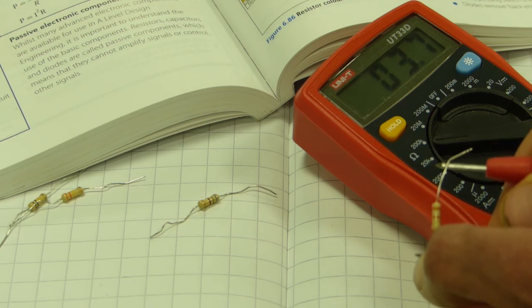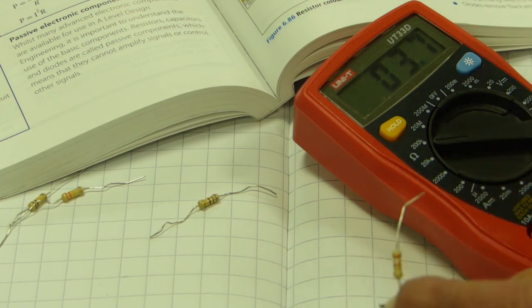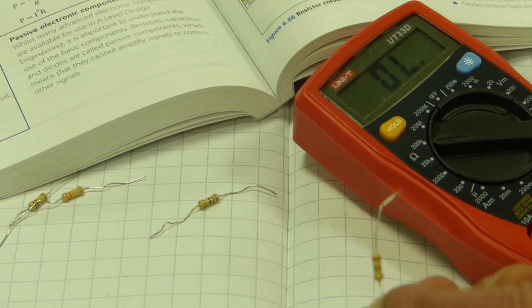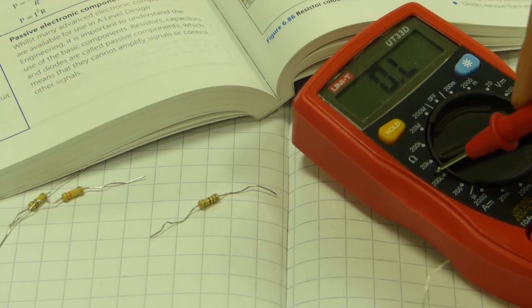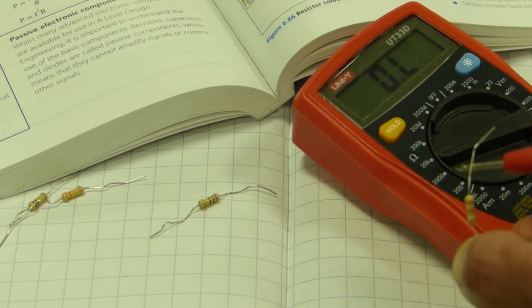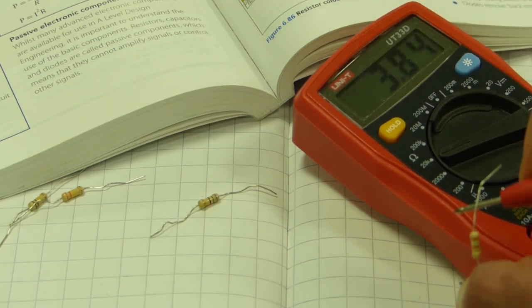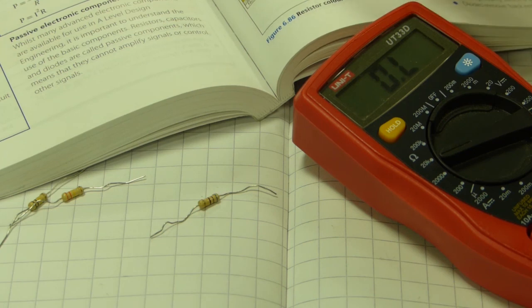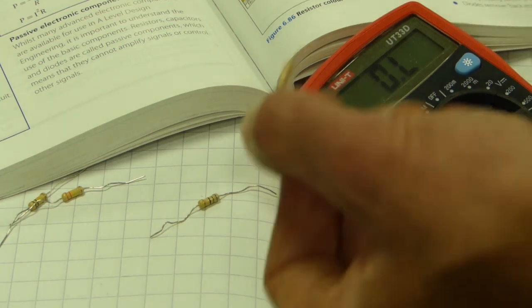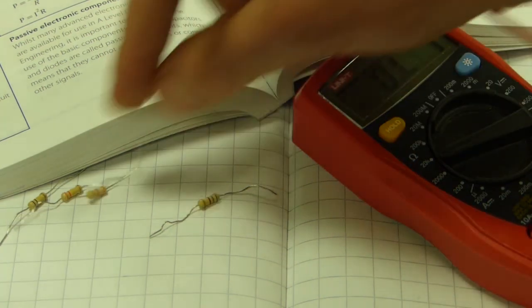So now, again, we're in a similar order. I'm going to go down. So it says 3.7 in 200k, so it should be 3,700k or thereabouts. But I might get a more accurate reading here in 20k, because it's still less than 20k, 3,700. And sure enough, I've got another decimal point there, so I've got a little bit more accuracy there. 3.84. Again, orange, white, red. So that's 3, 9, and red 100. 39 times 100, 3,900. Or sorry, 3.9 kilo ohm resistor.